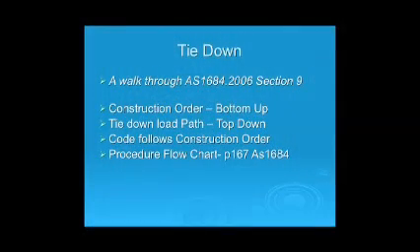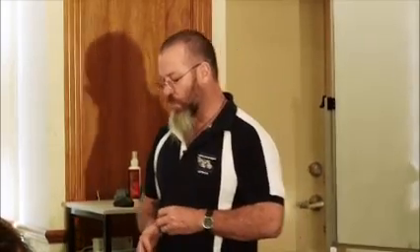Okay, so you're starting at section 9 at the back of 1684. Then bracing is section 8. And member sizing is basically everything that comes before that. So the first step is determine whether the fixings are nominal fixings or specific fixings.